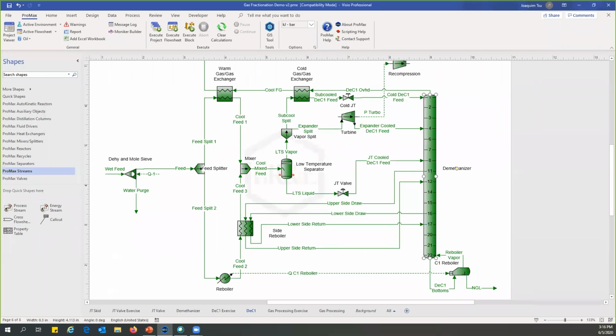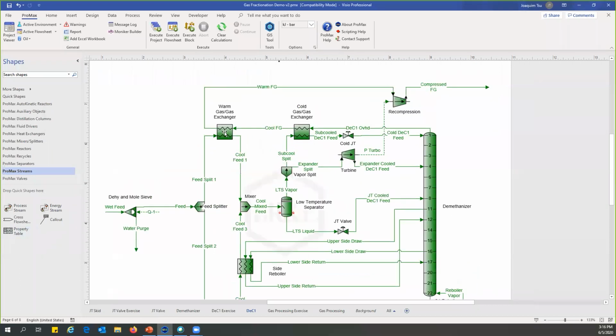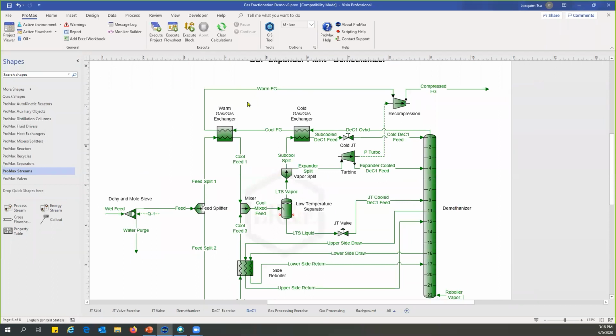So what types of heat exchangers are used over here? Generally, I've seen the more modern ones use compact heat exchangers. But admittedly, I've also seen shell and tube used over here, but the shell and tube heat exchangers are insanely massive because they can't get as close approach temperatures as, for example, a compact heat exchanger.